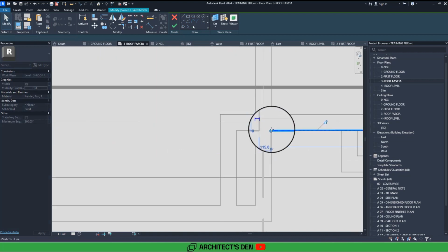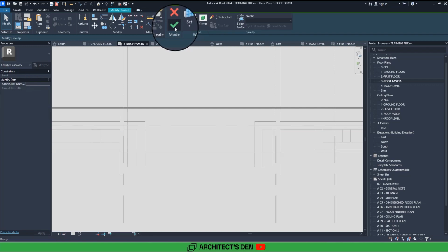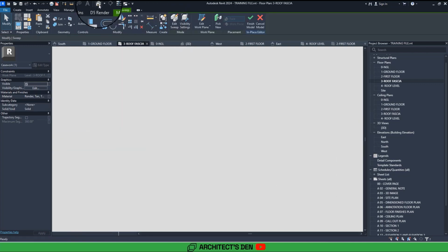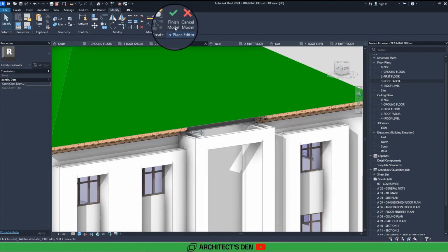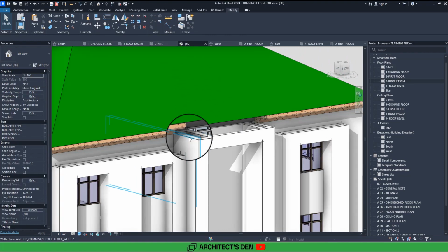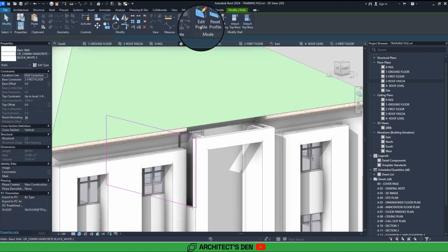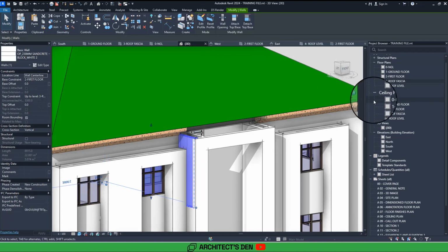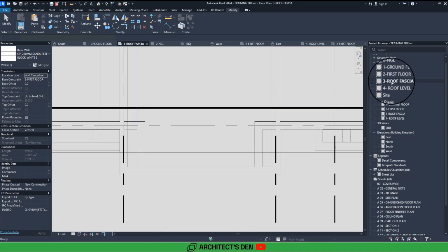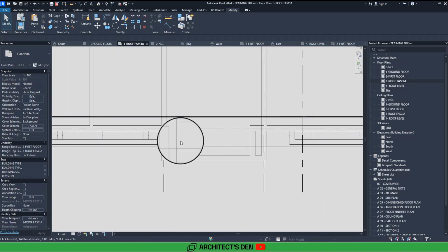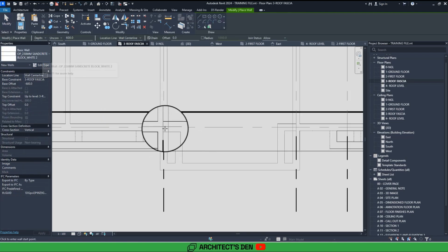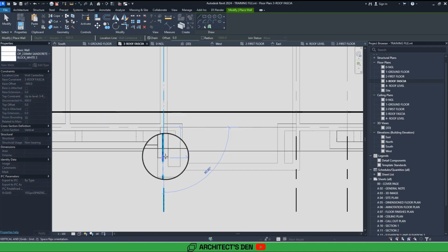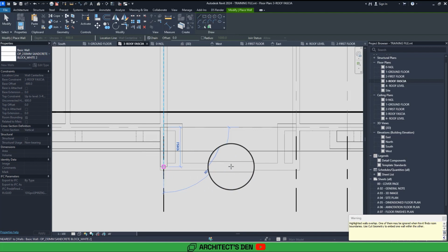So this is what I have in mind for the elevation. I'll click finish, it stops here. And this is good. Then I'll draw a wall on this level up the way. So I'm going to go to the roof fascia level on this floor. WA is a shortcut for wall. Make sure the right wall is selected, and then I'm going to draw this.